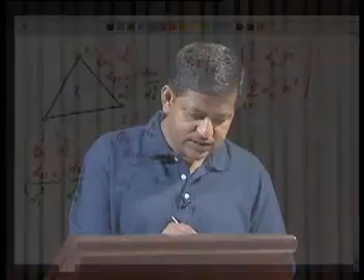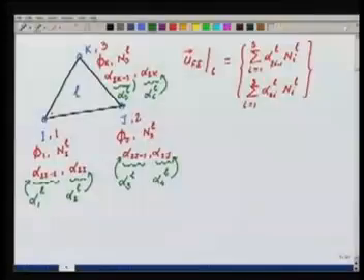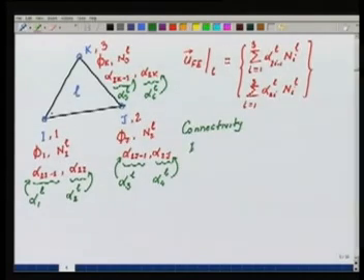Once we have this, we know this local to global enumeration, and we'll have to establish it. How will we establish this? This is when we do the degrees of freedom creation and numbering. That's where we establish this relationship. It's called the connectivity matrix, or connectivity information. This has to be created at that time, and this is not difficult to create for the mesh.